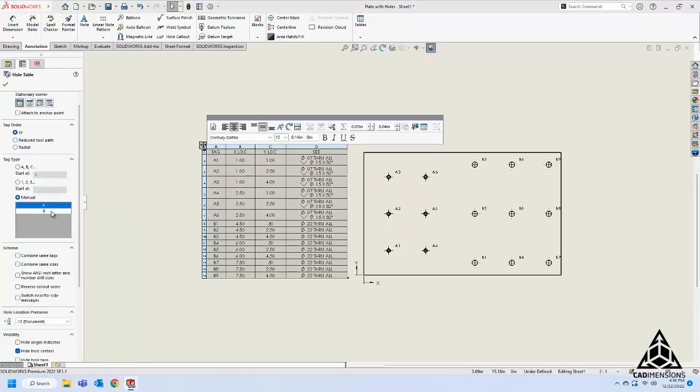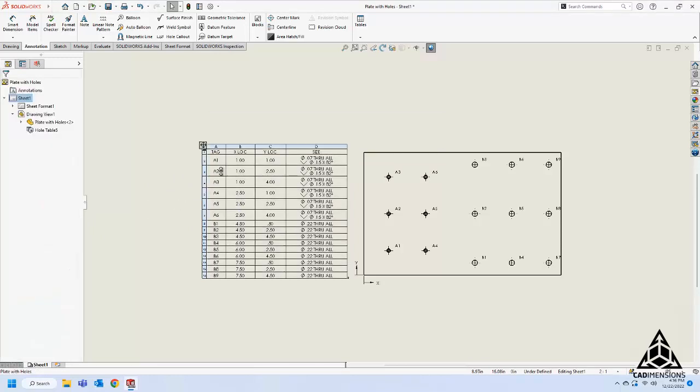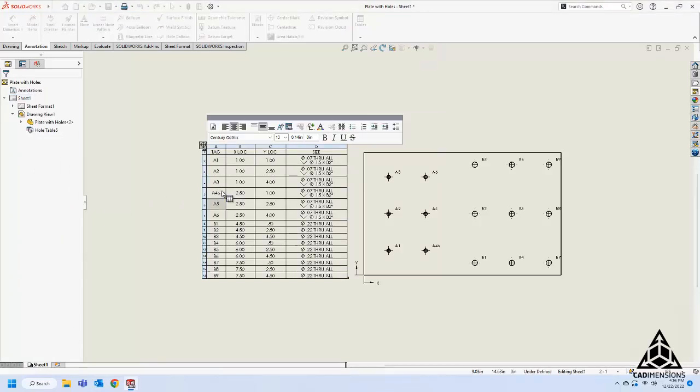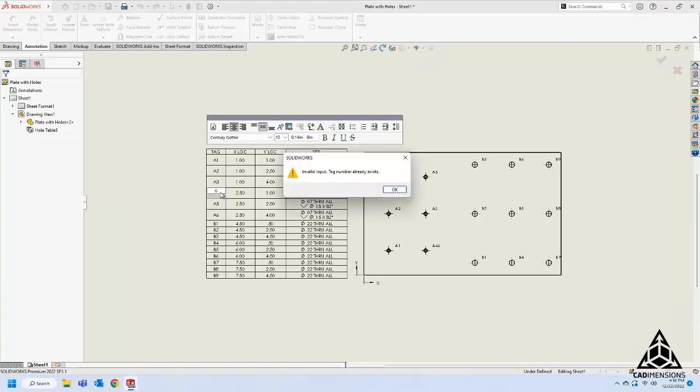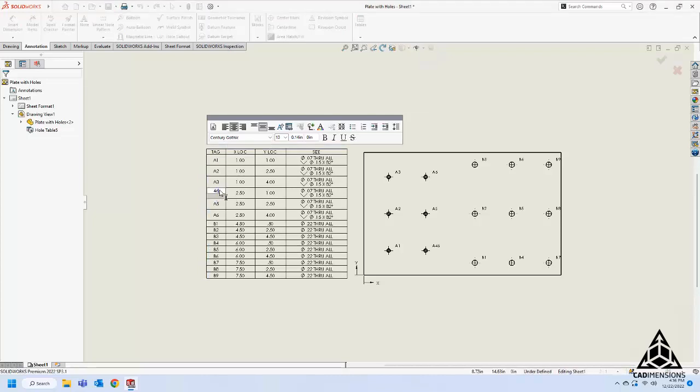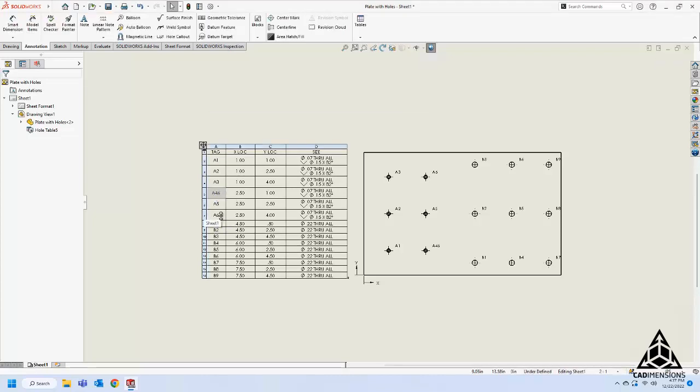And we're not going to be changing the letter yet. We're just going to be changing the numerical tag. So now you'll notice you can double click on this and change. Whoops, we don't need 46. You can change the actual tag number. Now here is the fun part. You actually have to generate a tag that does not currently exist. So you usually go 1 over what you currently have. Or in this case, I had 46 in there. That's fine. We'll just leave 46 for fun.